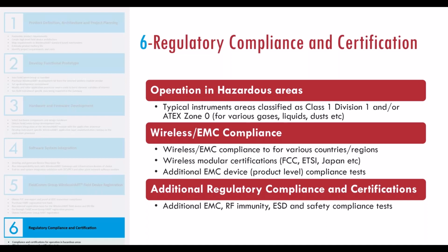already certified. Some additional regulatory and compliance tests that you will want to consider are some additional immunity tests, ESD, and safety compliance tests. And depending on the complexity of your instrument, if it's an intrinsically safe instrument or if it's an explosion-proof instrument, you will definitely have to consider that these tests will take a while and they're typically not very cheap. So this is definitely something you want to consider from the very start when you define your product requirements, which are obviously driven by end users and market demand.